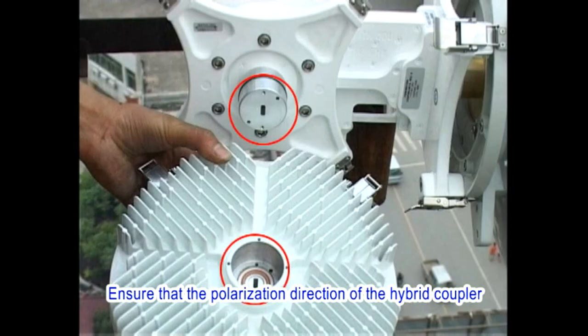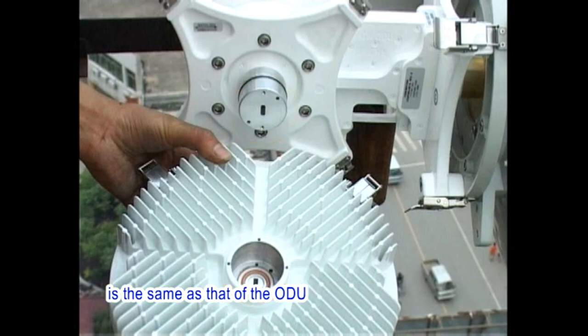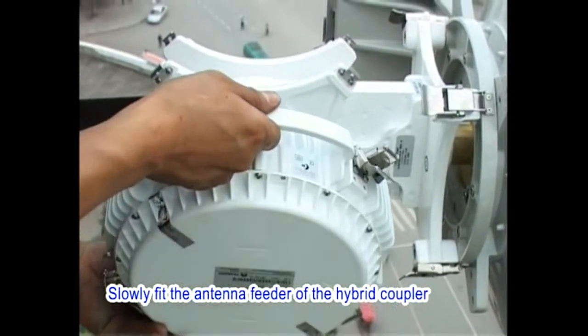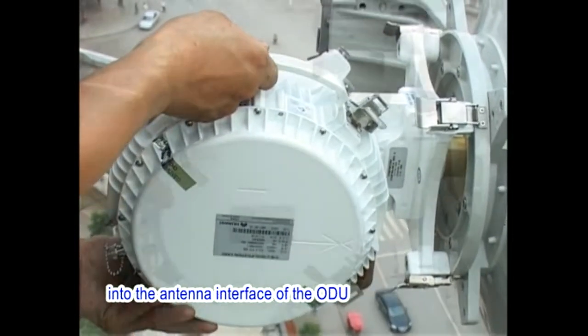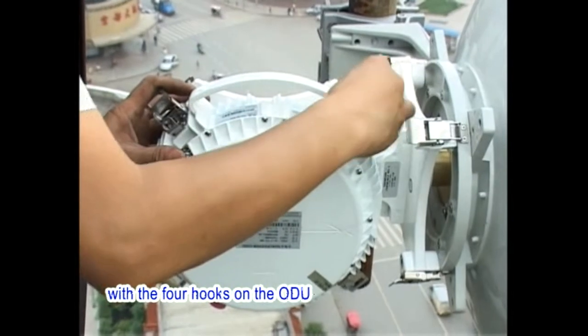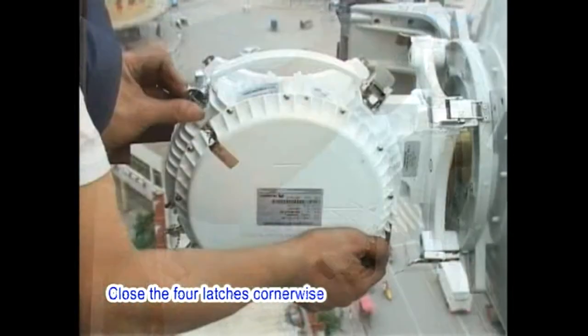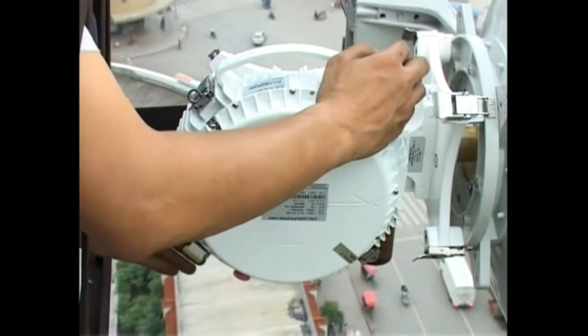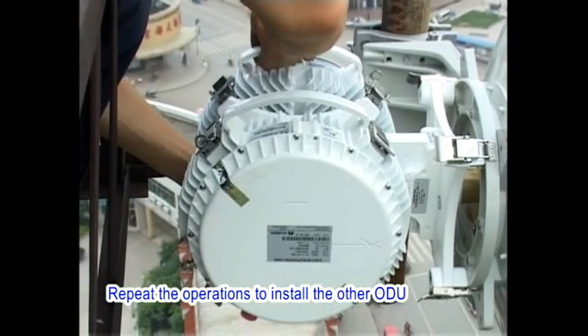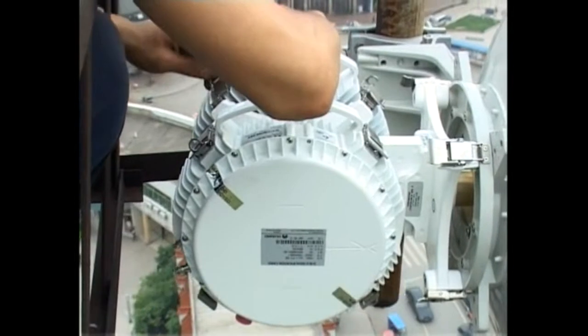Ensure that the polarization direction of the hybrid coupler is the same as that of the ODU. Slowly feed the antenna feeder of the hybrid coupler into the antenna interface of the ODU until the 4 latches on the hybrid coupler engage with the 4 hooks on the ODU. Close the 4 latches cornerwise. Repeat the operations to install the other ODU.